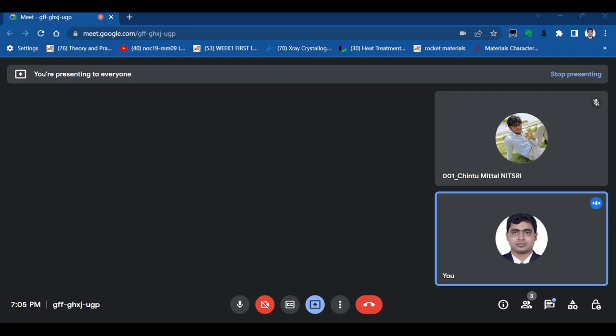So first let us have some idea about what the Tresca yield criterion is. If principal stresses are given, sigma max minus sigma min by 2 is our maximum shear stress. We can also see this if we draw a Mohr circle.